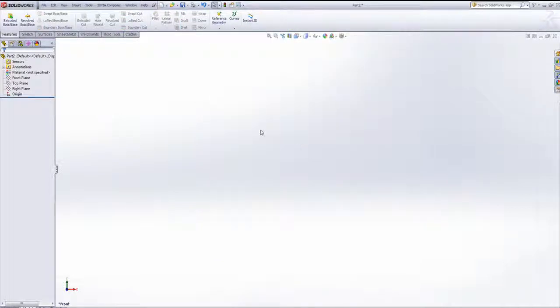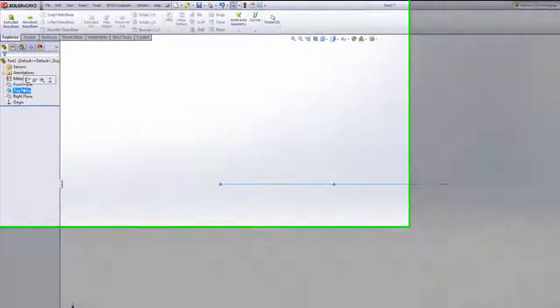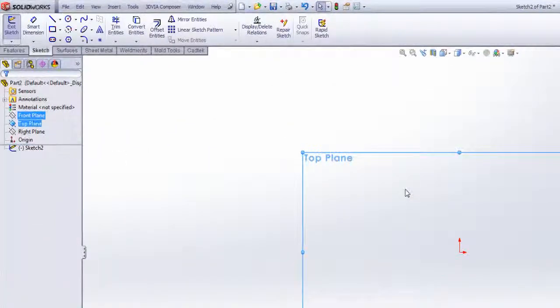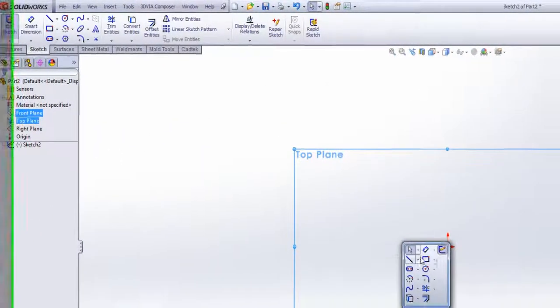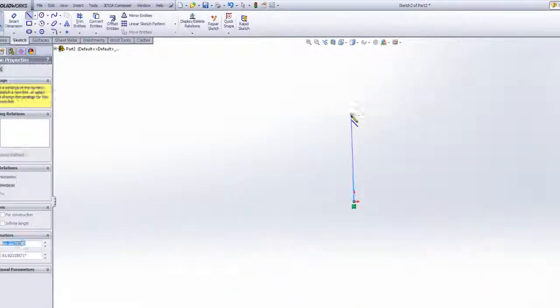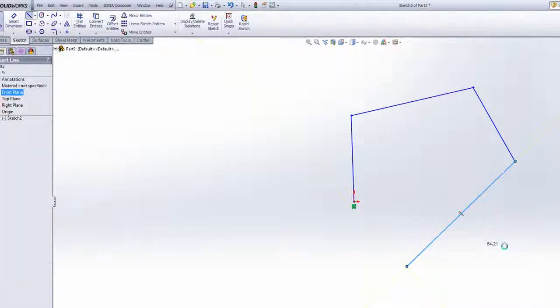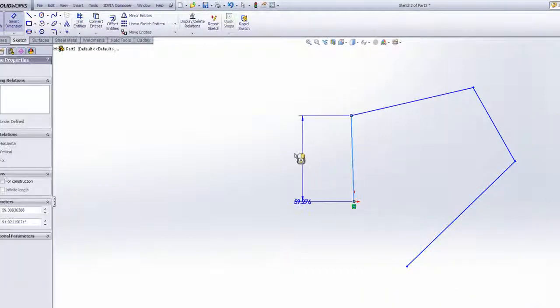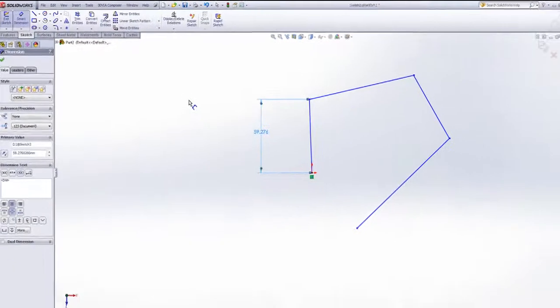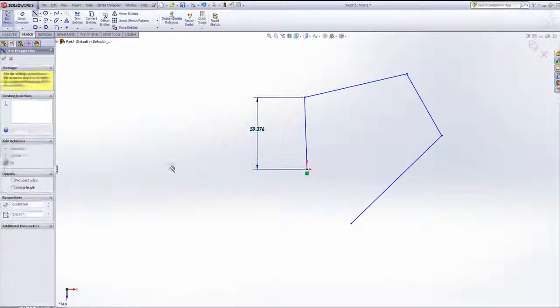If you combine this with the shortcut key, it means that I can get the shortcut bar on my mouse gestures, so I don't even need to press my S key. This means that when I'm doing my sketching, I become very quick and fluid, because I can simply go off, start to draw my shape. If I want a dimension, I hold my right mouse button and drag to the right, I then get my dimensions up. If I want another line, I can go off very quickly.